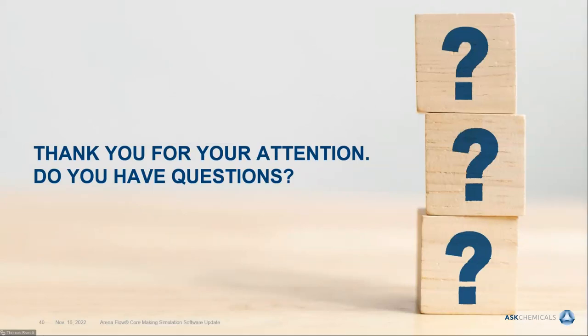Well, one question from my side. What's the kind of format that you need if you want to run a simulation? Are there different kinds of 3D modeling preparations needed by pattern shops or by the single customers, by the single foundries? That is a very good question. ArenaFlow itself, as an input, requires STL files. It does not read anything else but STL files.